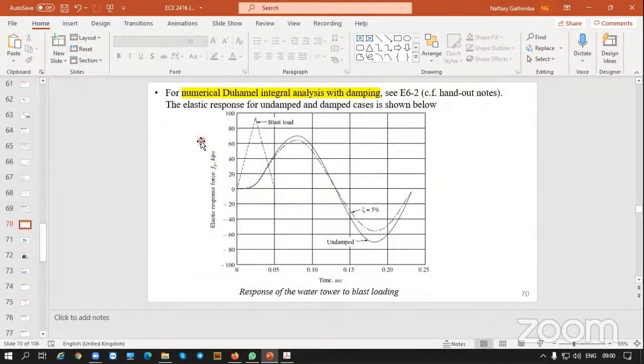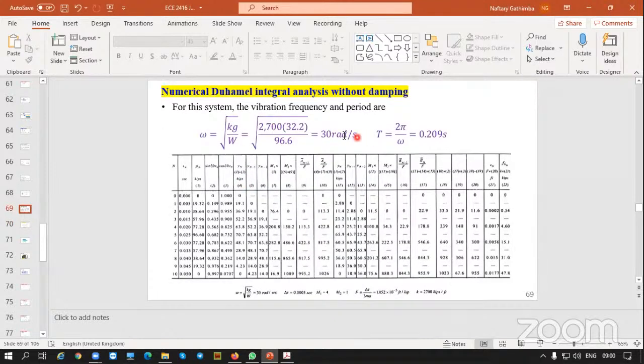Remember, you might be told to plot the response, maybe the displacement, but here we are plotting the force because you have already gone a step ahead to obtain the displacement, and then we get the stiffness. That's why this part was important, obtaining what the K was for different times for this structure. It was given in our equation.